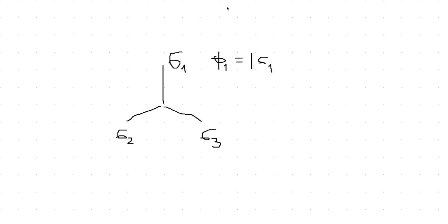So the Rankine type of criteria is one that you can present in a deviatoric plane. So this is the plane that is perpendicular to the hydrostatic axis. This is my principal stress sigma 1. This is my principal stress sigma 2. And this is my principal stress sigma 3. So you're looking from the hydrostatic axis there. And so basically, if you take the Rankine criteria, Phi1 is the absolute value of sigma 1 minus sigma y less than or equal to 0.